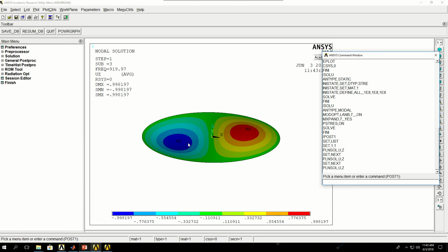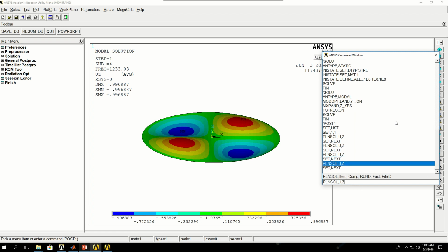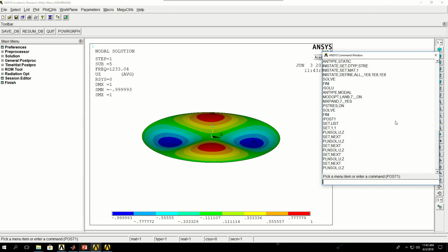So that's why we have 2 natural frequencies of the same value, but basically the mode shapes are the same. The only thing is that it's shifted by 90 degrees, which for a circle is basically the same, and we can ignore the duplicate natural frequencies. The same is happening to the next natural frequencies. So I have 4 points of peaks and valleys, which again, if I do NEXT, I'll see that they are shifted by 90 degrees, just like that. So I can ignore that duplicate.